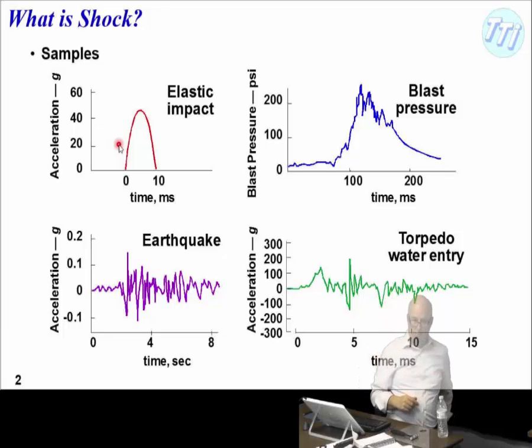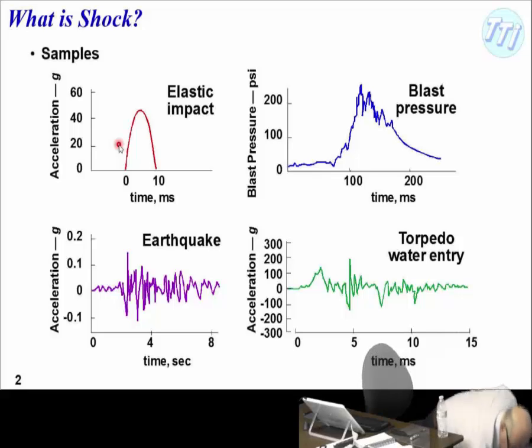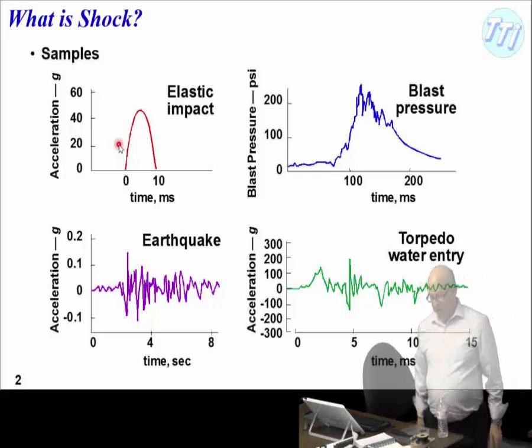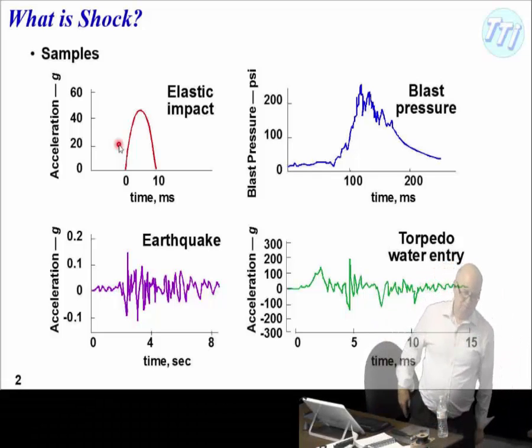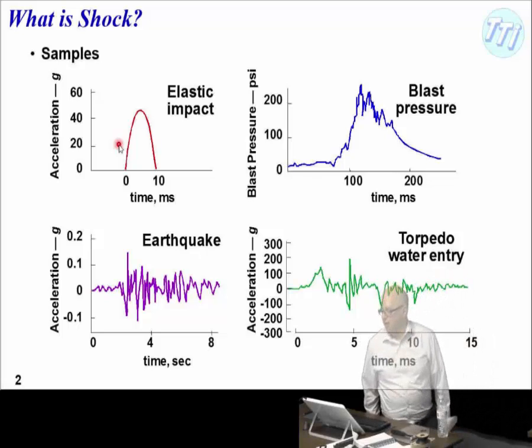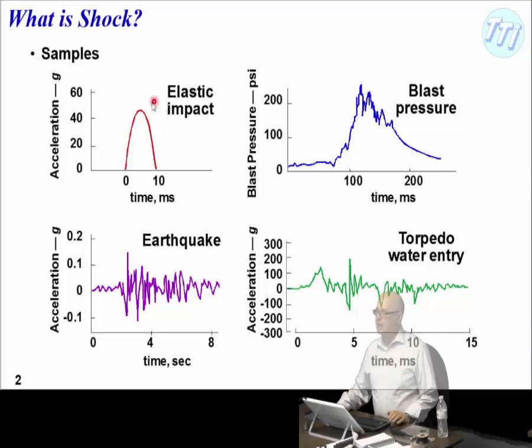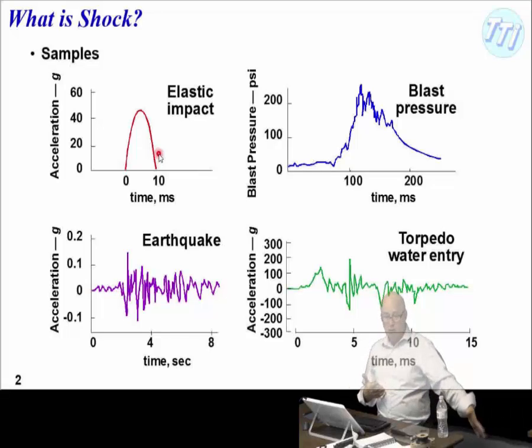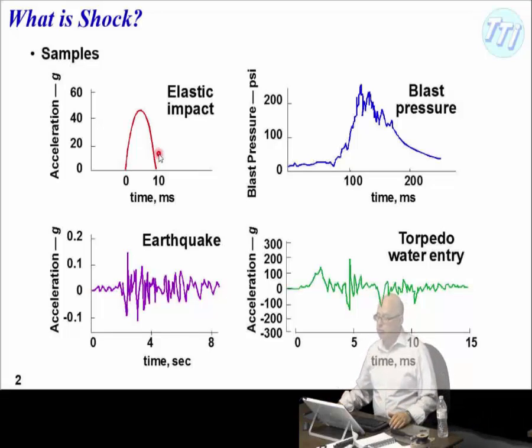Oh, I see what you're saying. Yeah, because the pre and post is not really. Yeah, you have to do stuff to it. Right, and we'll see why and how we do it. Let's do a half sine shock pulse. So here we got this nice half sine elastic. That's for anything where it's like hitting spring, rubber. This is fairly springy, and that will give us something like that.